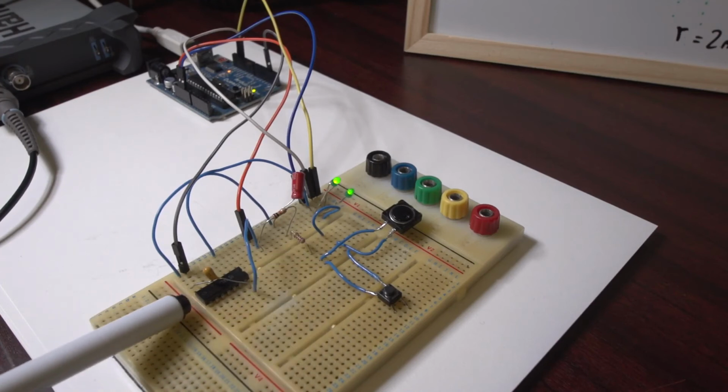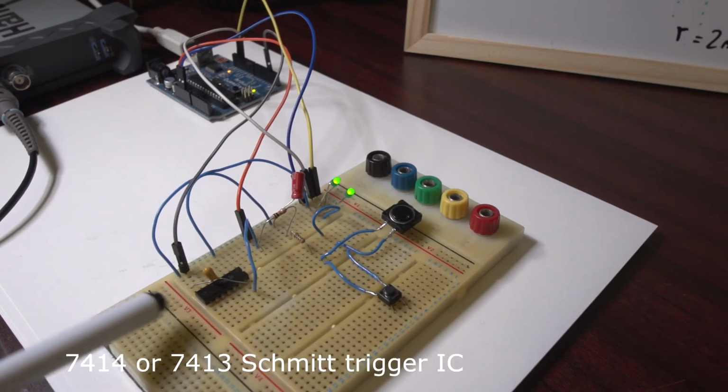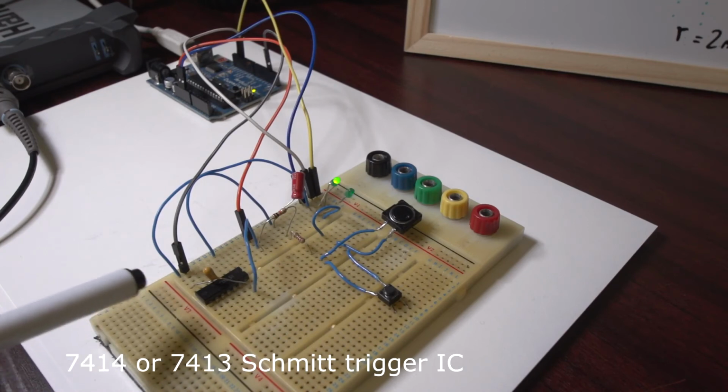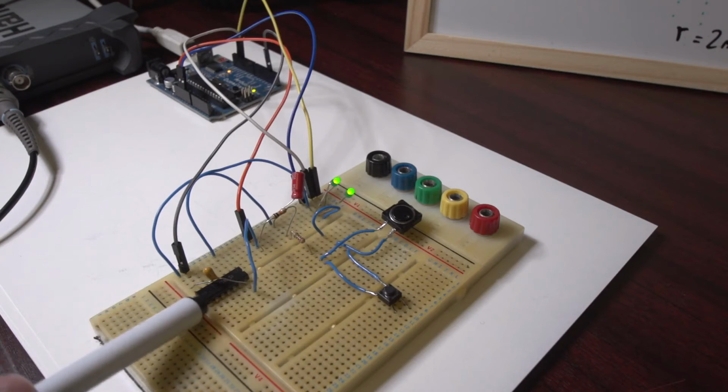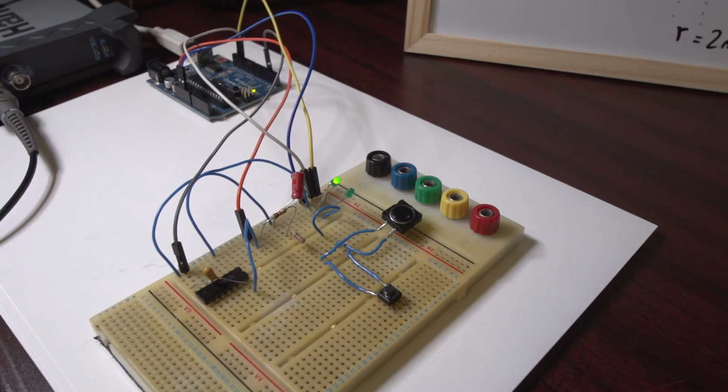And we've got a chip down here, and that's our 7413, which could probably be better if it was a 7414. It's just I don't actually have a 7414 to hand, so I've used a 7413 Schmitt multiple input NAND gates and configured it as an inverter. So it's doing exactly the same job as a 7414. It's still a Schmitt trigger, it's all I had. Okay? Sometimes that's what you have to do.